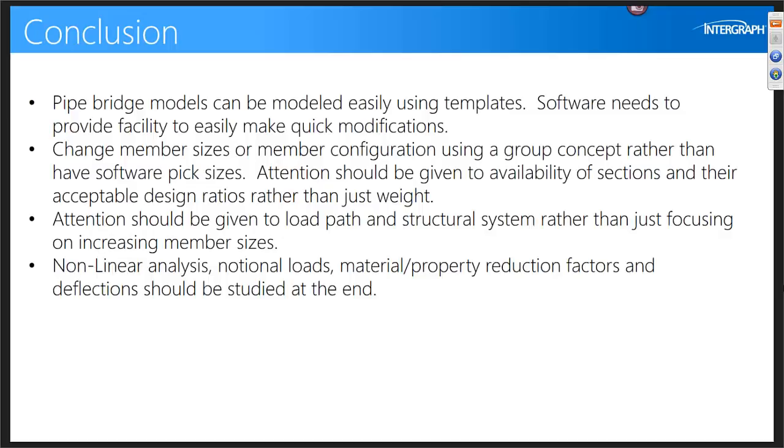But in absence of that, we had design guides to generate these wind loads. So GT Strudl does not do automatic load generation on piping, but you can certainly get that loading from other sources and apply it to your structure.